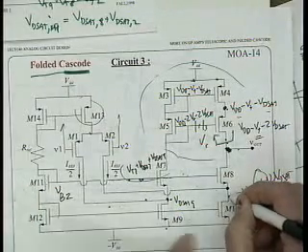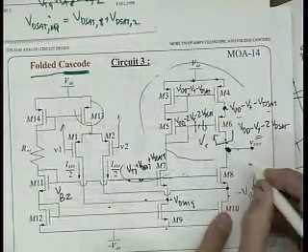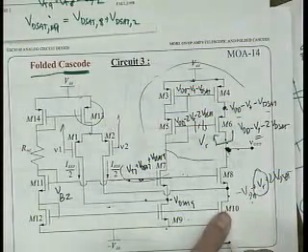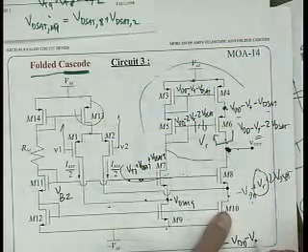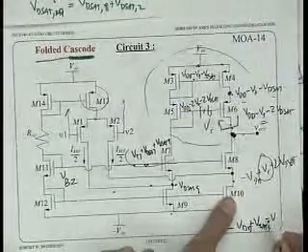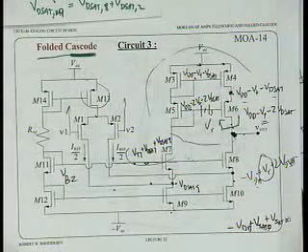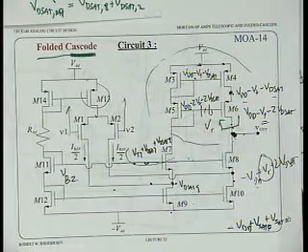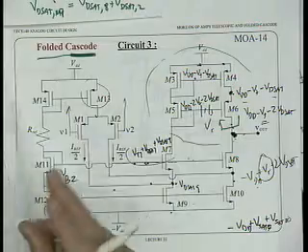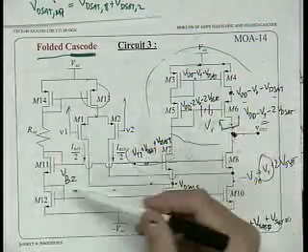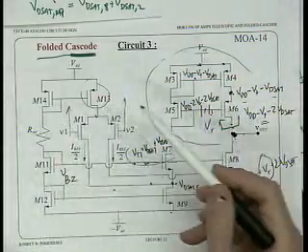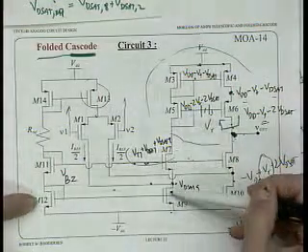This will be at VDSAT of 9. And this will be able to go as low as minus VDD plus VDSAT of 8 plus VDSAT of 10, right? But when we get input swing, the voltage at M13 will change. How come that doesn't change the voltage at the VDS of M9? VDS of M9.